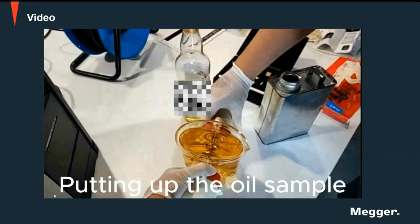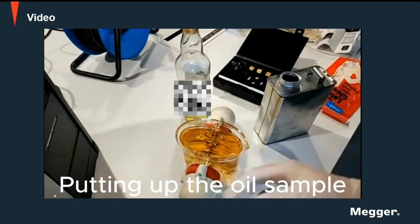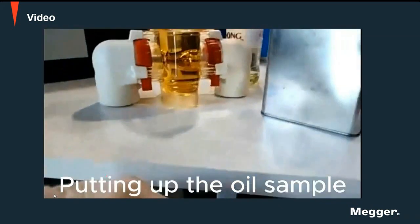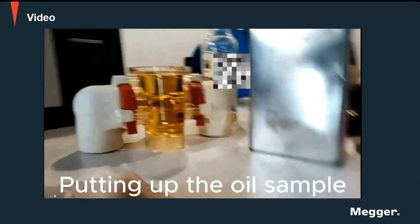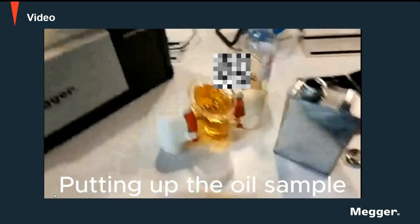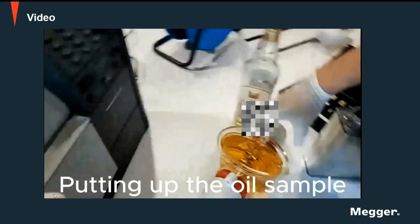We should top up a little bit higher than the limit, because when you put the lid over the vessel, it will press the oil to overflow a little bit, so that when we are testing, the air will not contact with the oil.